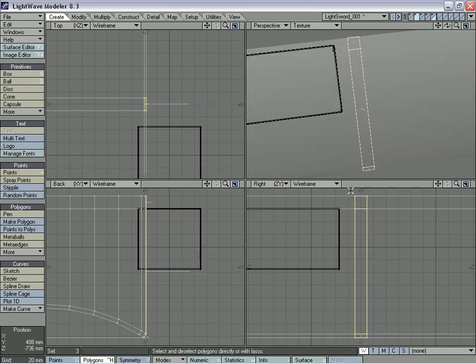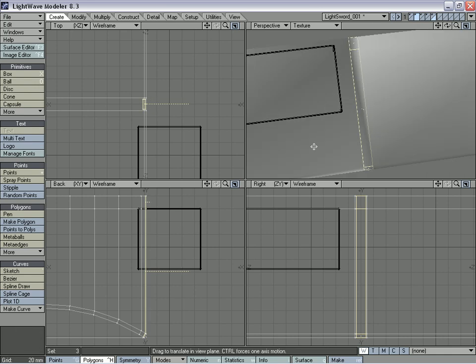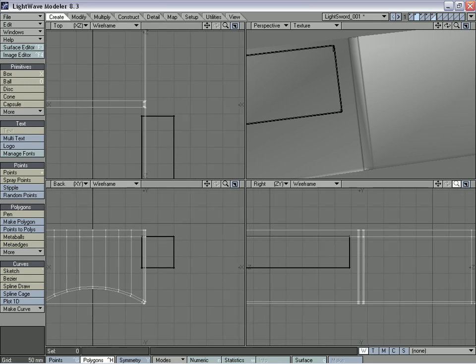We're going to smooth shift it. So Shift F, right mouse click, and use stretch, which is H on the keyboard. Pull it in just a little, and then use T to move it in just a little, and then smooth shift it again, stretch it in just a little bit more, and move it. And now you've got that definition.